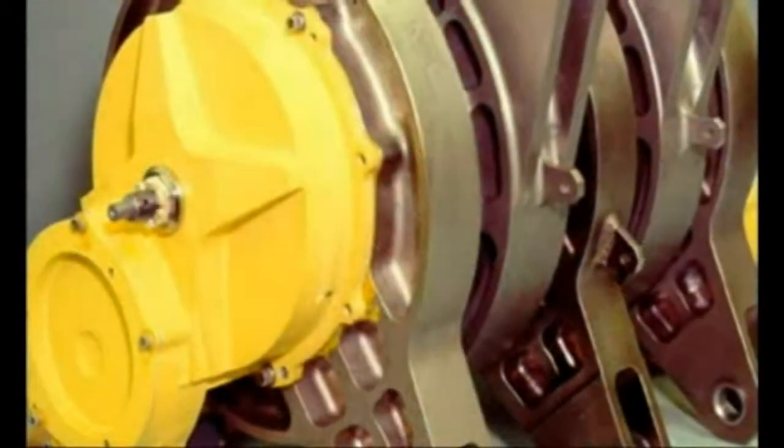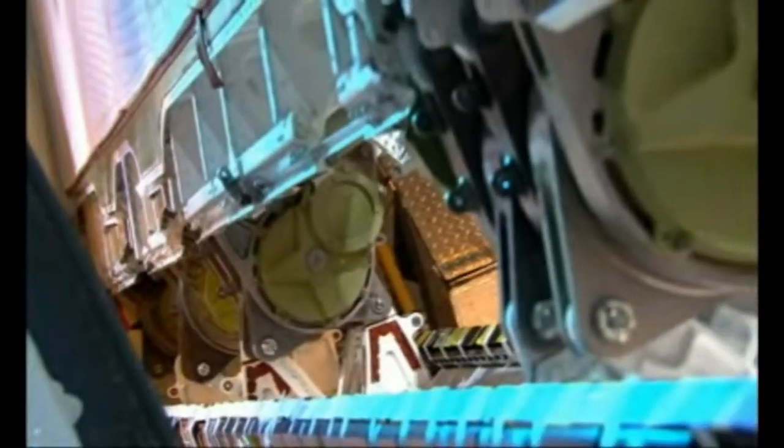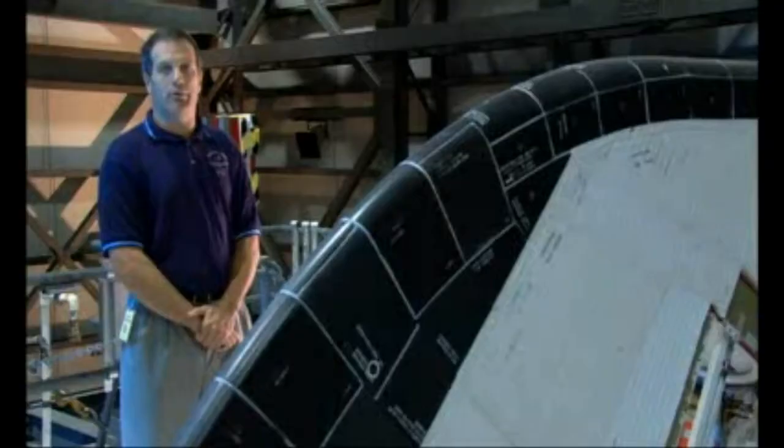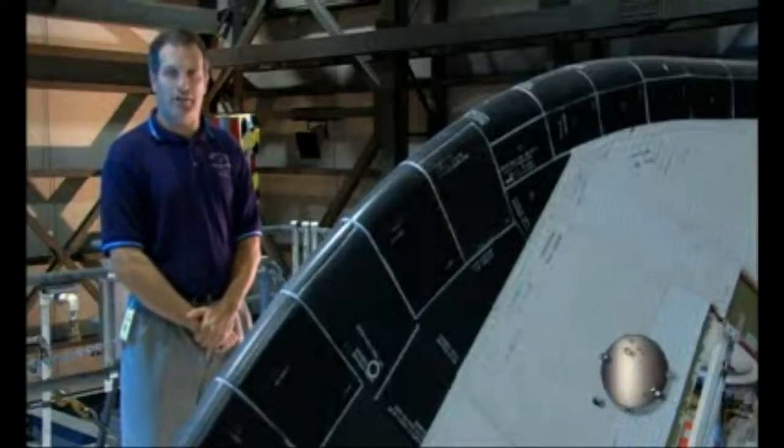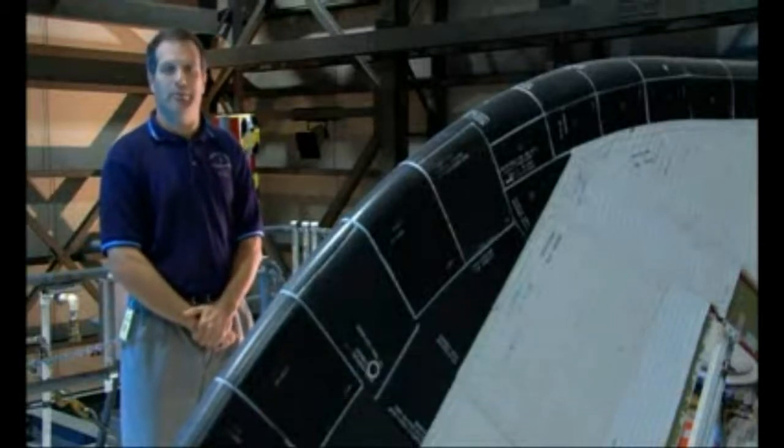Painstaking and time-consuming examination of all of the actuators revealed the reversed gear problem in an actuator installed on one orbiter and one spare actuator assembly. The incorrectly installed gears reduced the overall strength margin of the actuator and could have resulted in a critical failure had the gears broken during flight. Fortunately, the affected flight actuator was located in a lower stress position in the overall actuator configuration. We were lucky in this case that it was the lowest loaded actuator that was put together incorrectly, and as a result we didn't have any problems.